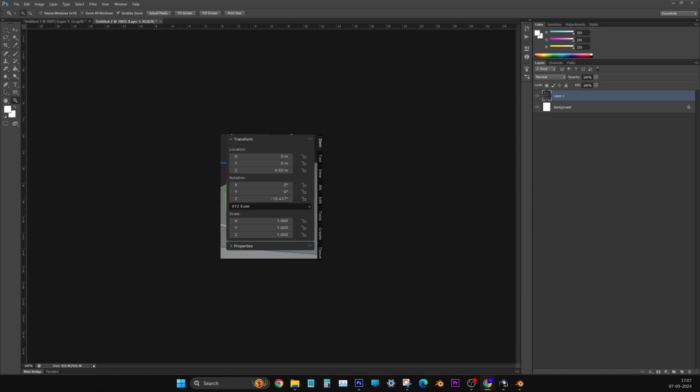Right. Now we have to reduce this gap. How? Just go to local. Now here, you have to select the empty. Only the empty we are going to deal with. In the cube we are not moving or rotating anything at all. Right. Minus in rotation Z, minus